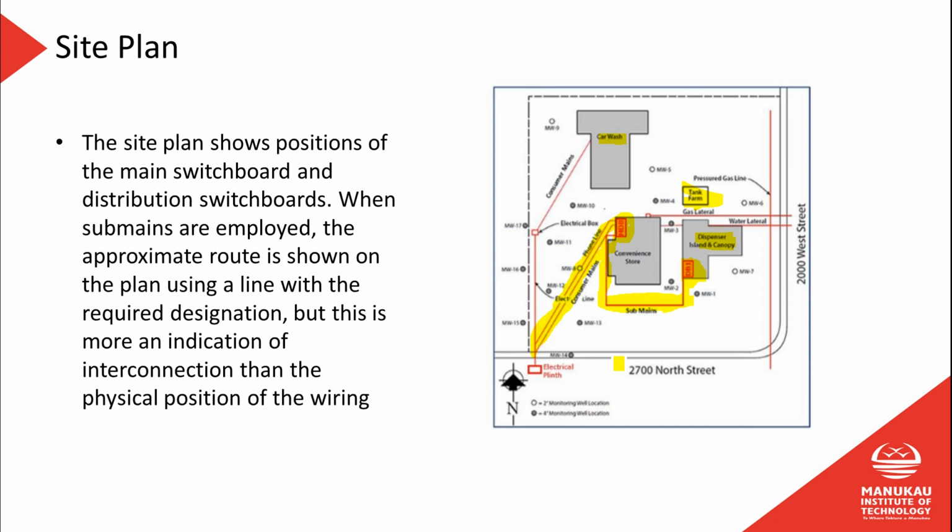And when we started digging, we found that the people who had done the installation saw on the site plan that they needed to run that 50-meter duct, but they figured that no one would ever know the difference, so they just ran about 2 meters of ducting from each end. So it looked like there was a duct there, but actually there was nothing in the middle, and they probably saved themselves, I don't know, a few $100 worth of pipe. So don't be like that. And if you're going to do something like that, put it on your as-built drawing, because then somebody who comes later will appreciate that you actually wrote on there that you didn't do it.